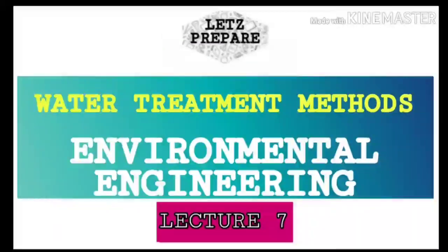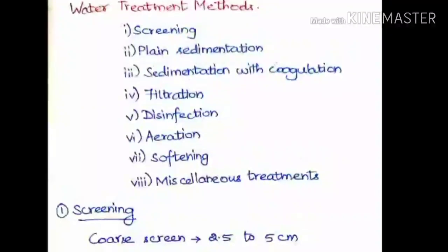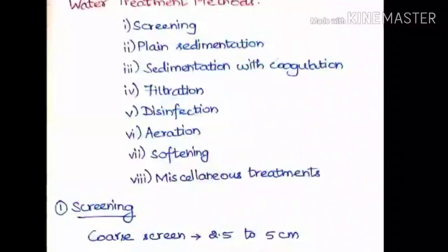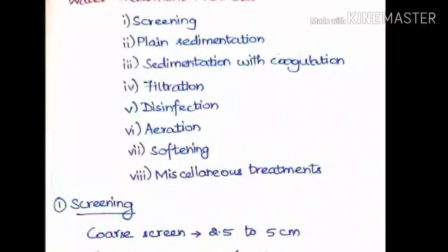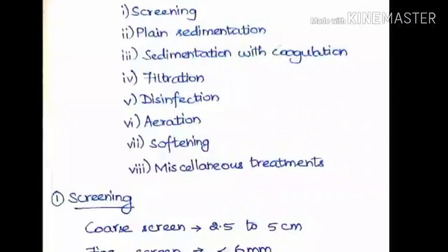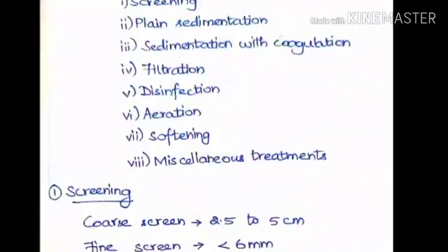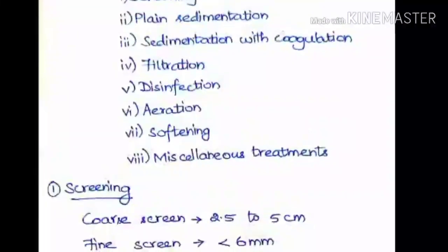Let's prepare on water treatment methods. So there are several methods for the treatment of the water. They are listed here: screening, plain sedimentation, sedimentation with coagulation, filtration, disinfection, aeration, softening and other treatment methods also. First we'll be seeing the screening.